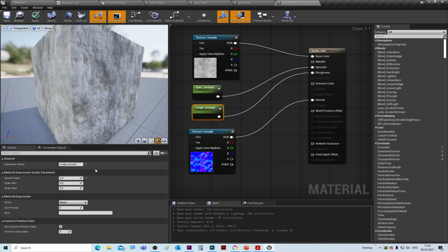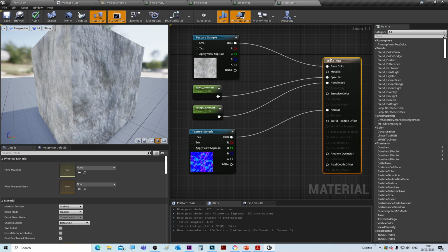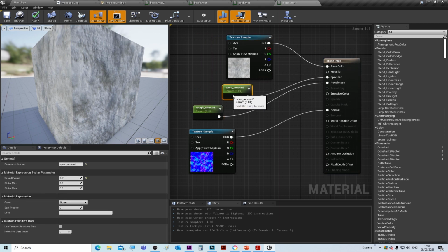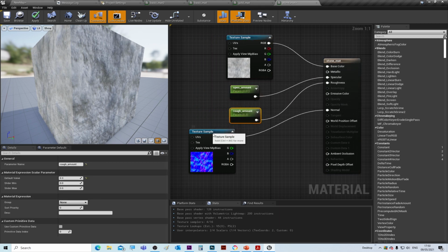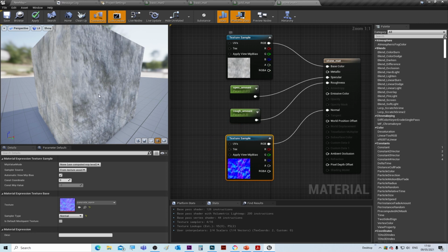Okay, so we're going to look at how the UV mapping is handled. At the moment, by default, on this cube, that texture is being stretched across the surface of each of those sides. But we need a way that we can tweak the UVs or the texture coordinates.